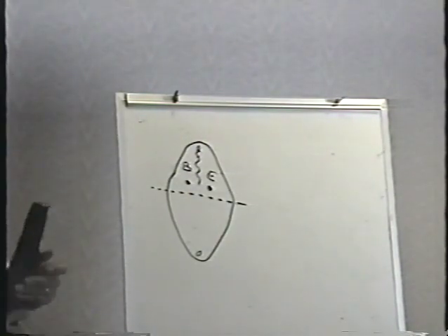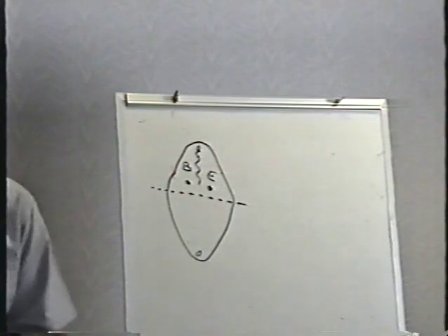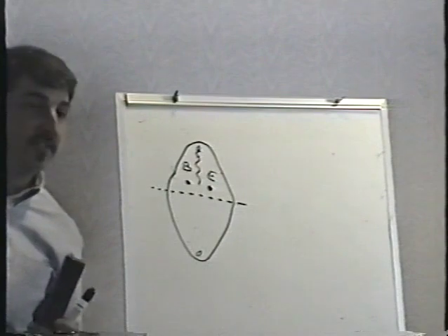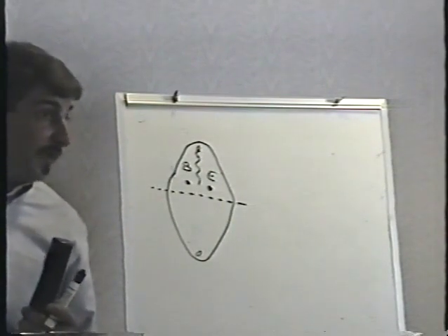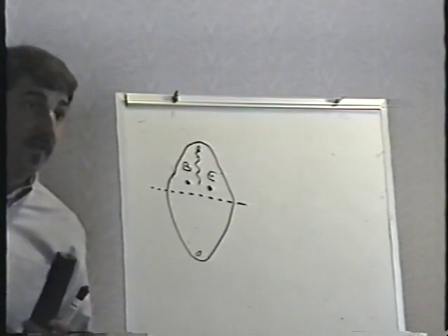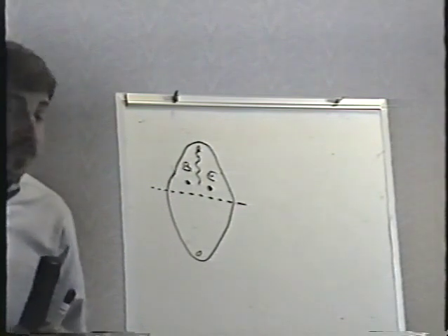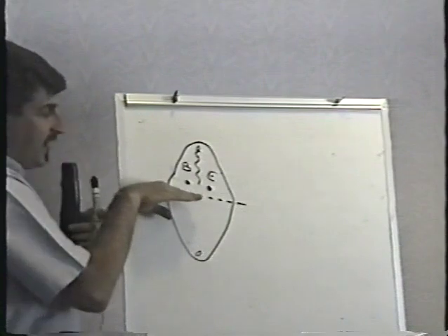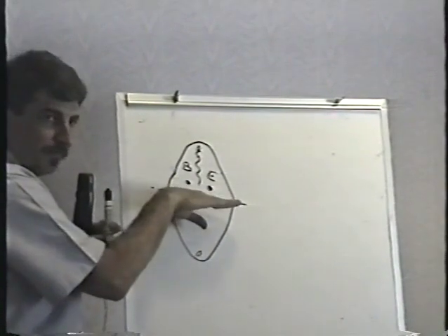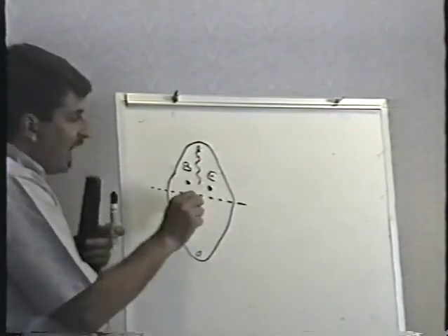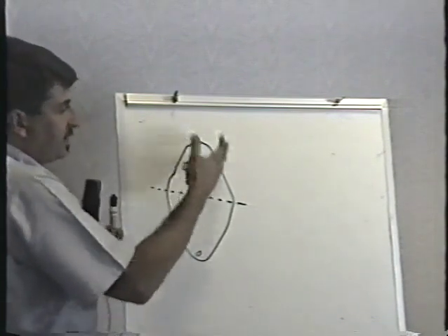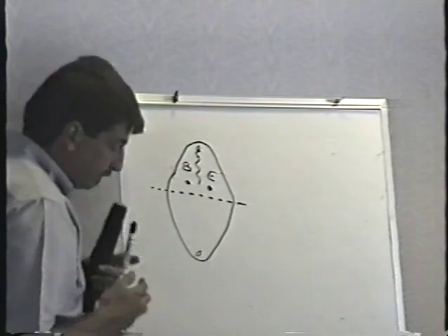You're not going to be able to see the bottom of these transistors because they're mounted on things like this. You can't see the bottom without taking it off, but you want to be able to test it without pulling it off. You get what I'm saying? So the only way you can tell which lead is which is to look carefully. Those leads are not right in the middle. They're slightly offset, and if you hold it so they're offset above the center line, it's alphabetical order: base, collector, the case, and emitter.